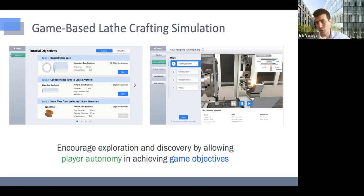Maybe you forgot to turn on one gas, or maybe something is going wrong at a certain step or stage of the equipment. So we think that for advanced students who are already familiar with the standard procedure, having this knowledge of the tool might give them additional insight to diagnose and troubleshoot their equipment if it goes wrong, and also look at the data coming out, the refractive index profiles of the fiber preform, to see, is this what I would expect, and if something's gone wrong, what might be going wrong. So they can raise the red flag to the engineer to come over and say, hey, there's something going wrong with the equipment, and I think it might be this element that's causing the failure.